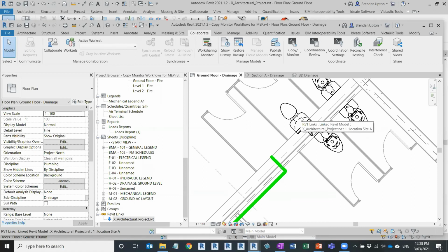Okay, someone's saying further to that as well that Revit will readjust the pipework. So yes, that potentially could happen, which may not be great. So perhaps the recommendation here would be, if you're going to use this workflow, maybe use it early on in the project to get fixtures in. Once you've got a fairly heavy design, you probably don't want to maintain that monitoring towards the end of the project. You can stop that monitoring down the track once you've got a large design and network of pipework in there, because you don't want it readjusting and moving things.